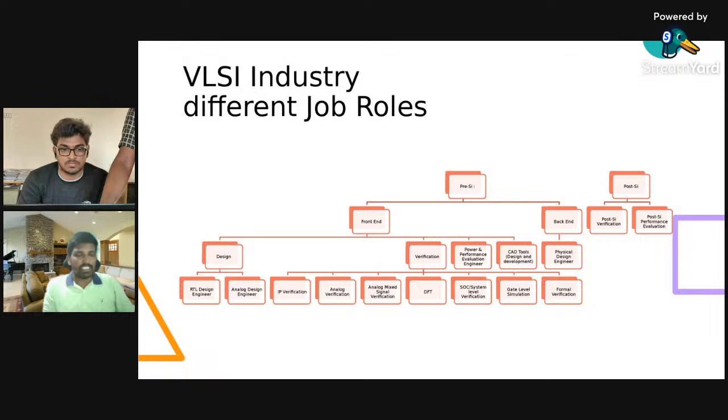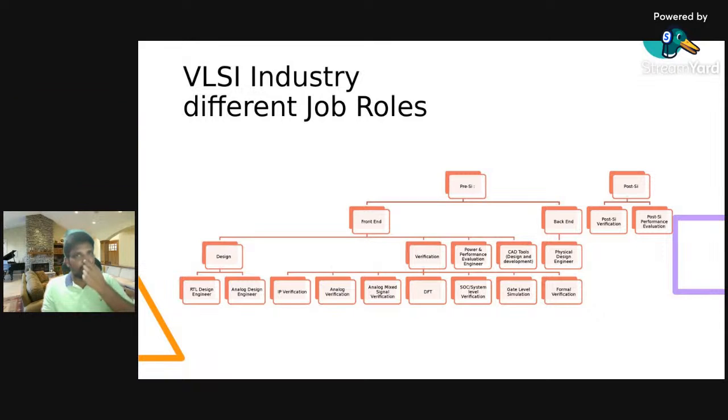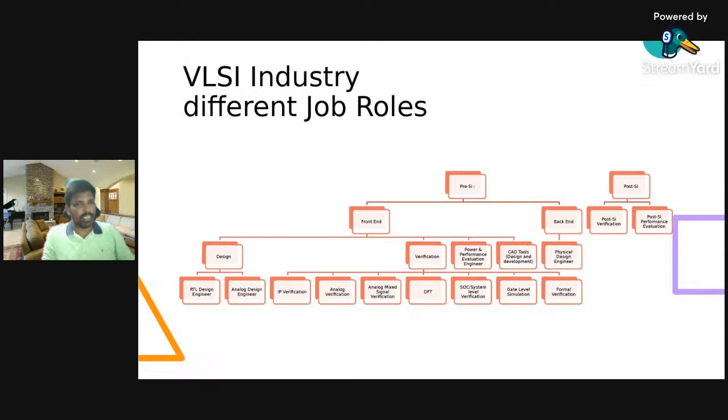And we have gate level simulation. Gate level simulation helps us in fixing all the timing related things, like the setup time and the hold time, and ensures that we do not miss any timing criteria. We have gate level simulation, and various engineers are also involved.